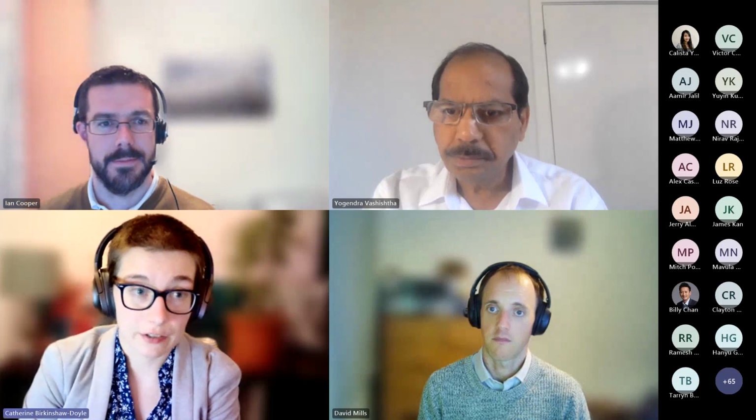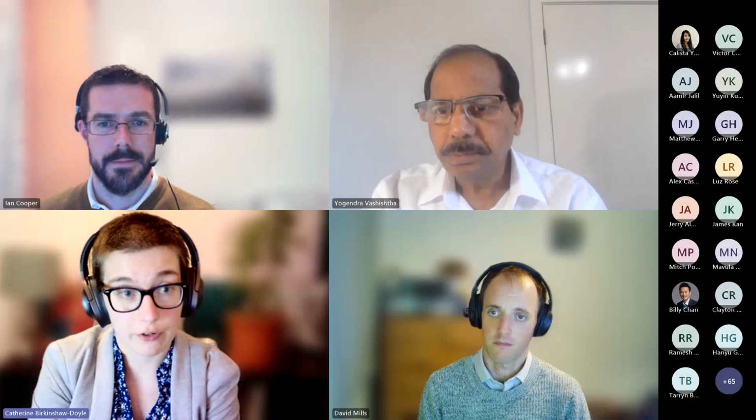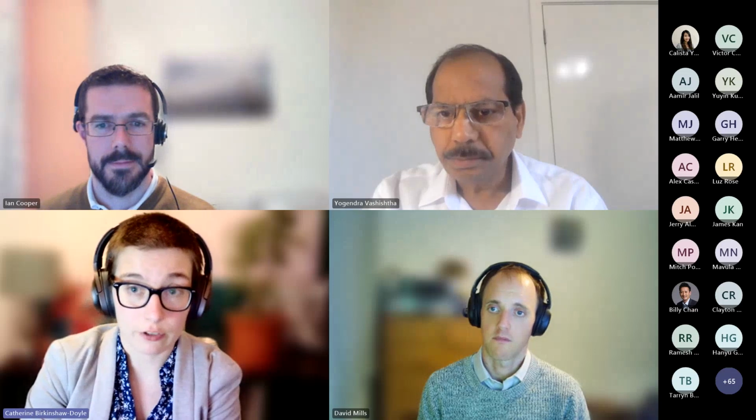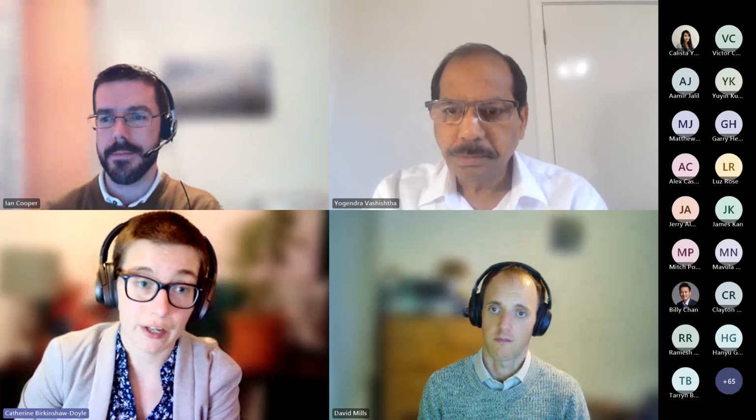Absolutely, yes. When it calculates that minimum demand, maximum generation run that I referred to briefly earlier, it does calculate the volt rise on the network. It does also do this during the maximum demand run to account for the effects of volt rise due to unbalance across the 3 phases, but primarily this will be due to generation. And you can see the split of these 2 effects in the tool. There is a dedicated volt rise section in the results pane, so you can isolate this result in particular.